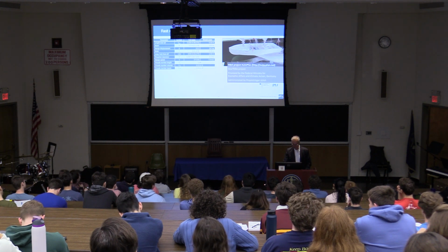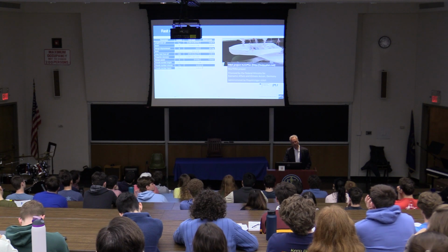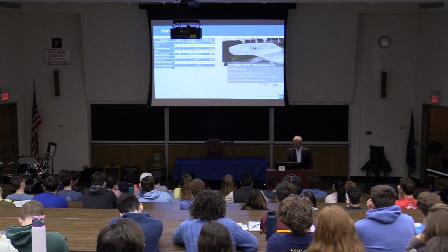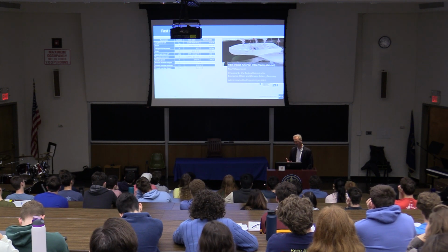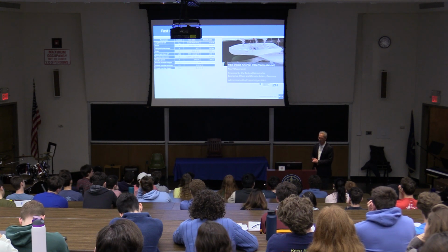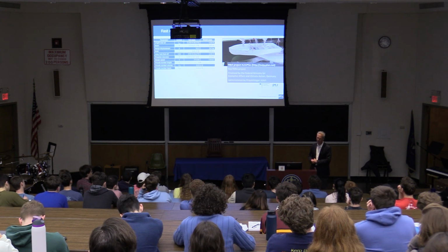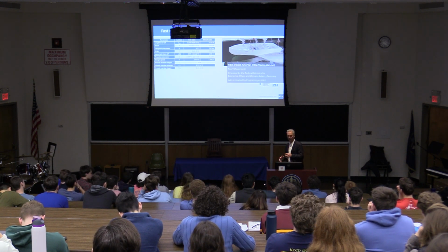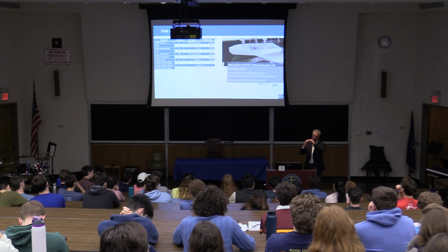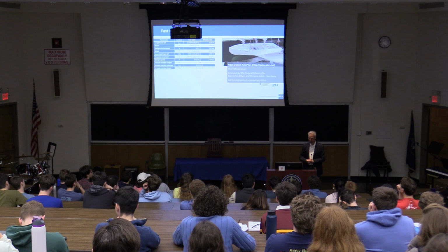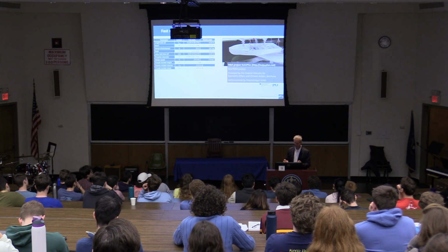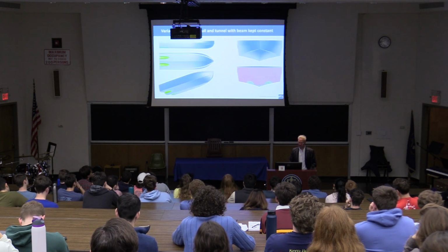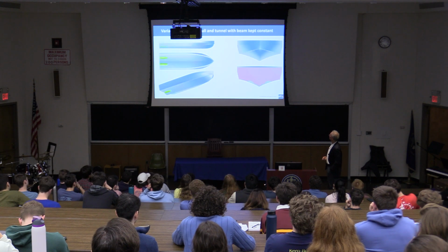For the hydrodynamicists, it means that we are a bit above the critical point of being planing. When you take the volume Froude number, if you are above 3, we typically say it's planing, or if you have the Froude number based on beam, it's a little bit above 2, 2.4, and this is also an indication of planing. There are a few other indications, like the center of gravity goes up, we have a cleared transom. Okay, it's at the lower region, but even more so, you have to optimize. Okay, let's have that quick look now.